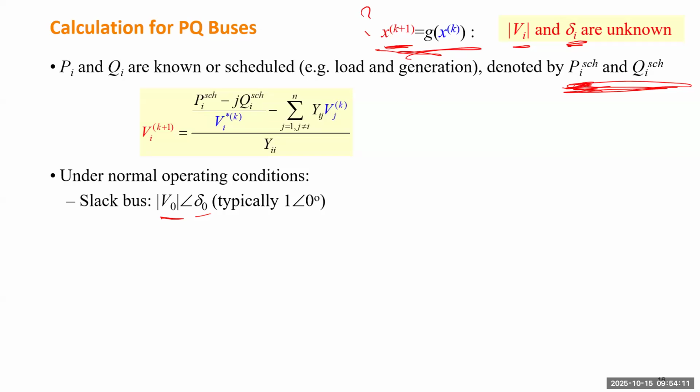For that equivalent bus, the voltage usually will be very close to a nominal value, right? 1. And you can use whatever angle for that system as 0 as a reference, because when you define a phasor, you can make any angle be your reference. So you make your large neighbor the reference. So that bus can be treated to have the voltage phasor 1 all the time.